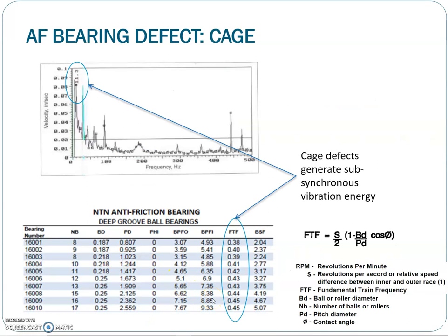We have previously discussed faults in the anti-friction bearing in the non-synchronous vibration topic. There are BPFO, ball pass outer race frequency, BPFI, ball pass inner race frequency, BSF, ball spin frequency, and FTF, fundamental train frequency. Please note that faults associated with the outer race, inner race, and ball are usually higher than 1 time and fall under non-synchronous vibration components.